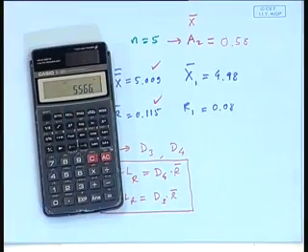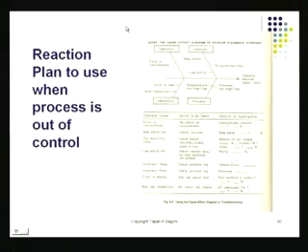If you've got wrong data there, that has now gone into your process and it's caused this variation there. What you do is you recheck your calculations. So I've listed that because it was in the cause and effect diagram. I do the calculations there, redo the calculation, and I turn to the process and make sure that I've done all the rechecking and so on, and I mark right here, have I found the problem? Calculations correct? Yes. That means I need not really worry about this factor, then go down to the next one.